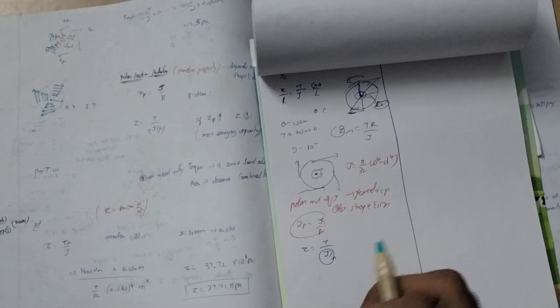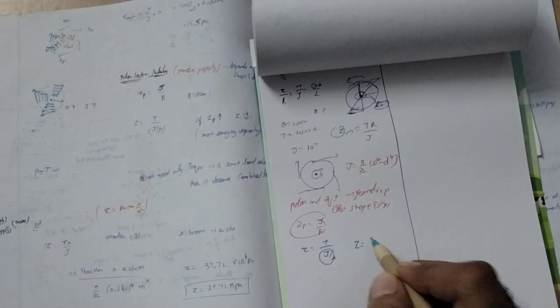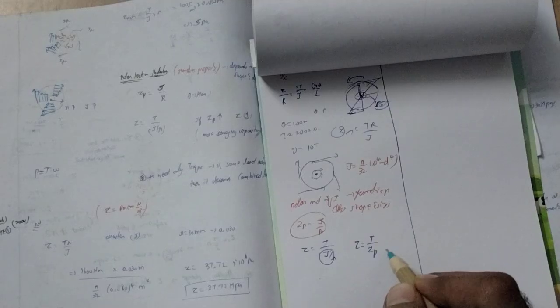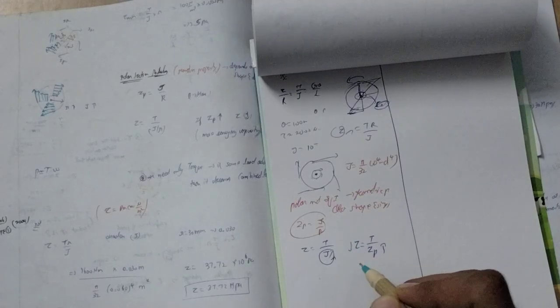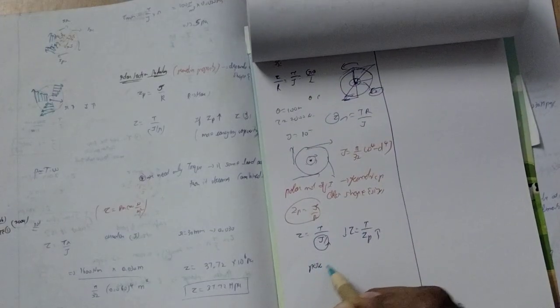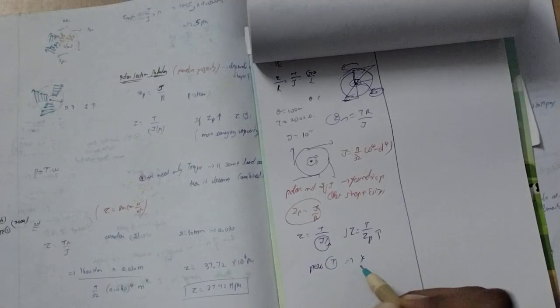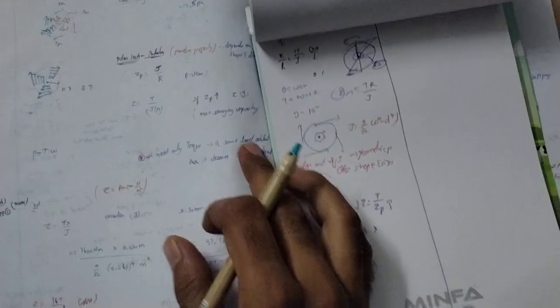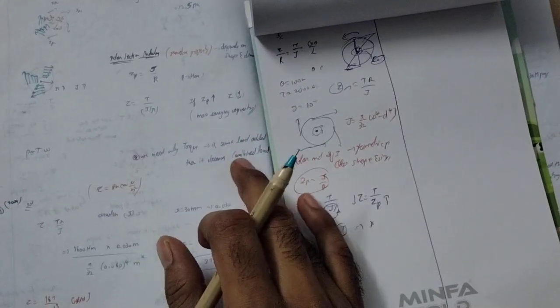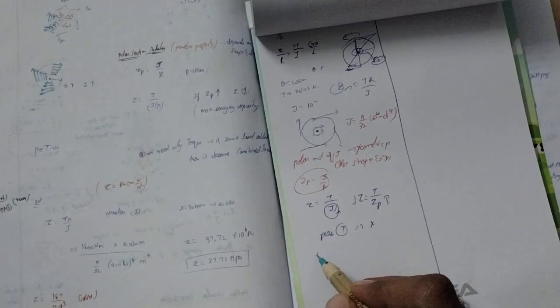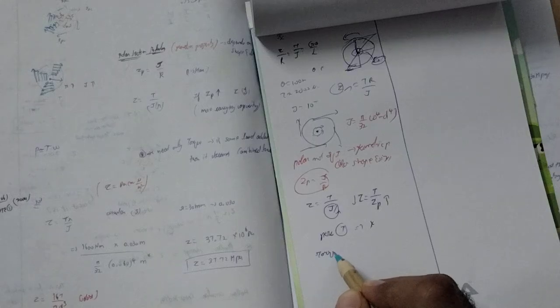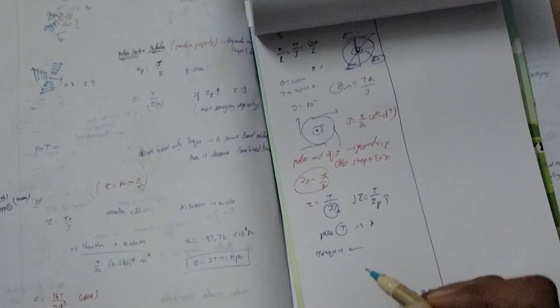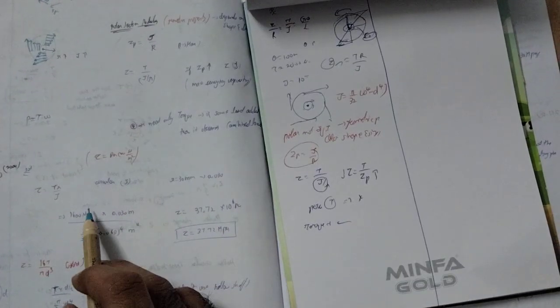You can see the shear stress equal to torque divided by Zp. If Zp increases, shear stress decreases. If the polar moment of inertia is high, the shear stress decreases. So we need only torque, and if some other load is added, then it becomes a combined load. Yes, definitely, if torque plus any other kind of load is added, it is going to be a combined load.